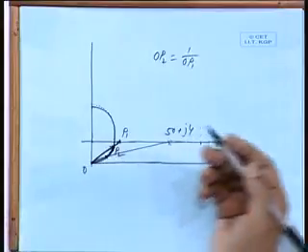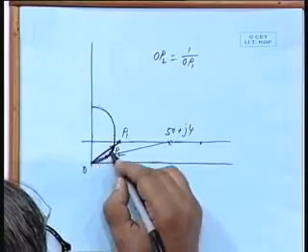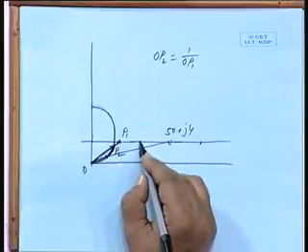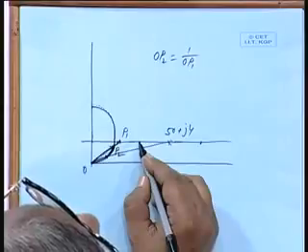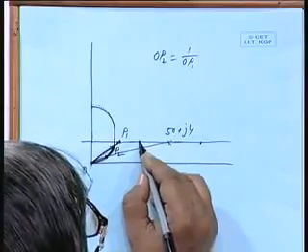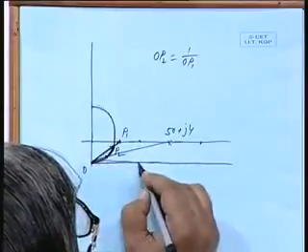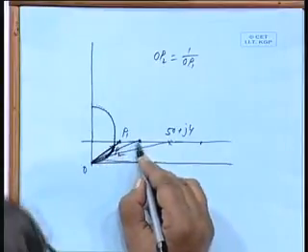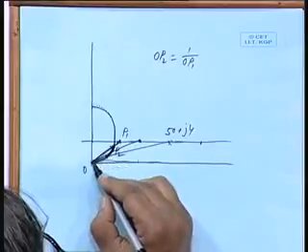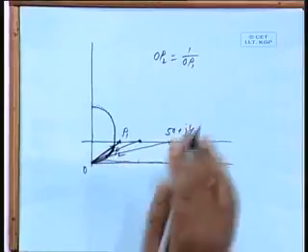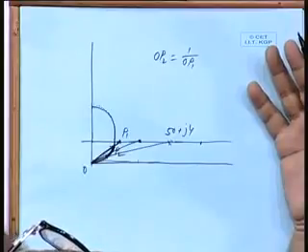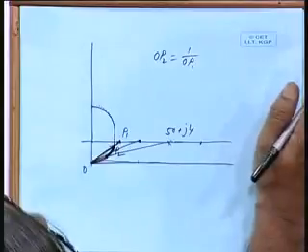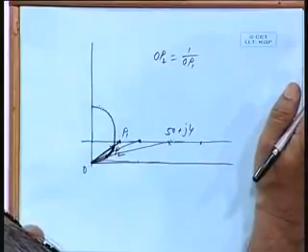So, you can now multiply for any particular location. If I want to calculate the current for 10 plus j4, suppose this is 10 plus j4, this is the point. So, draw a line; wherever it intersects, this is the length of the vector which is already magnified 40 times. I have taken a scaling factor of 40. So, that has to be divided by 40, is that all right.